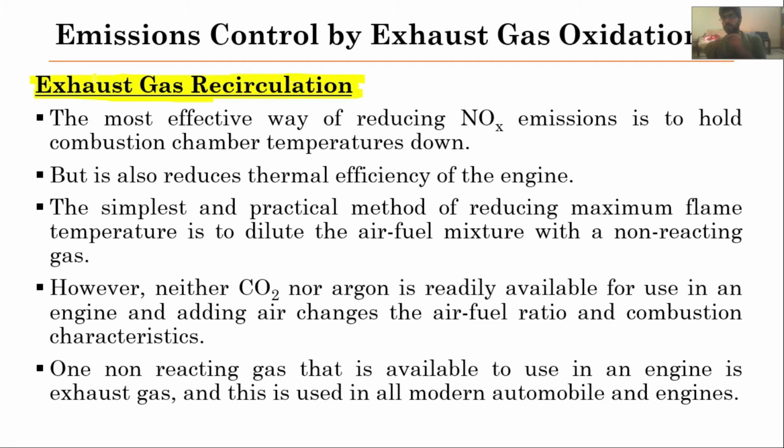When we recirculate these exhaust gases back into the combustion chamber, they absorb some of the heat energy generated during the combustion process, and they also dilute the fresh incoming air, which therefore reduces the maximum flame temperatures. And since the maximum flame temperatures have been reduced, no further emissions of the nitrogen oxides will occur.